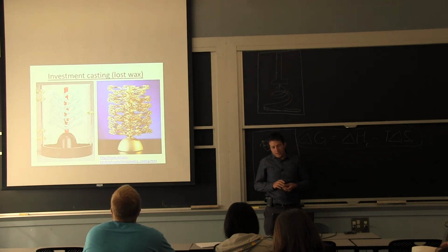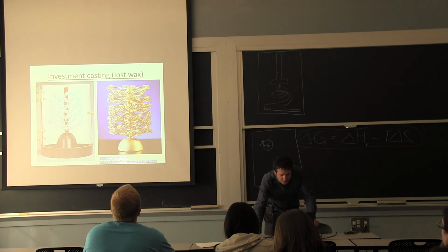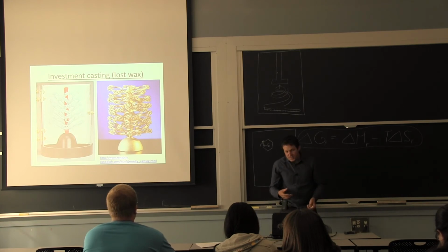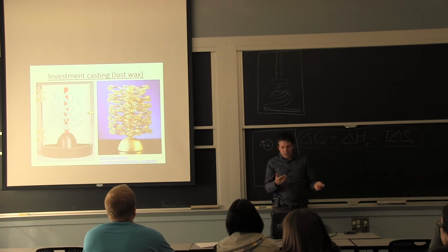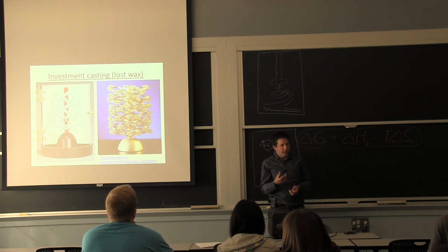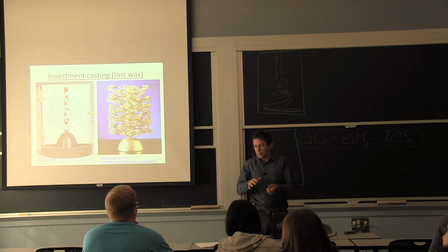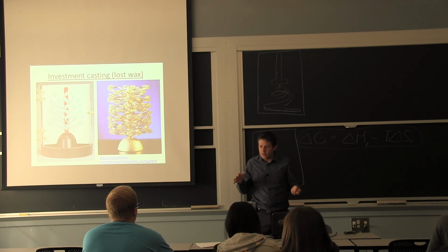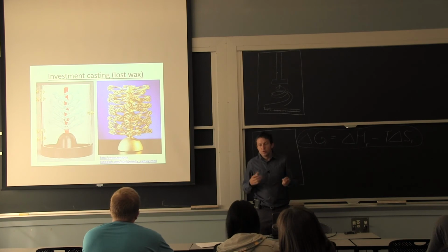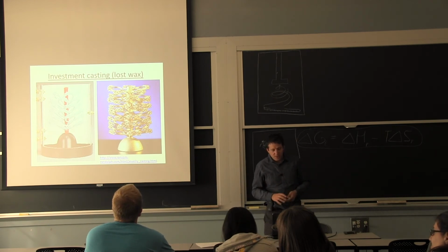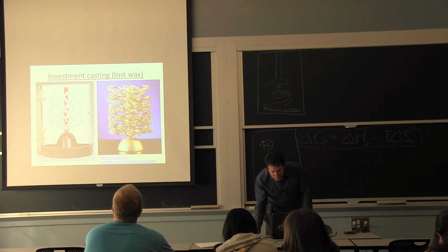The jewelry stuff, you can see here in more detail this riser and the different parts as a mold. The difference here is it's so intricate, if you look at that left side image, that you can't expect to be able to recover your pattern. I talked about sand casting as if you put it in, you get your stuff set, you take it off, and then you cure your whole mold. Here you lose it, and that's why we call it investment. You invest in your pattern and you're going to have to make another pattern the next time around. So that's the reason for the word investment casting or lost wax.